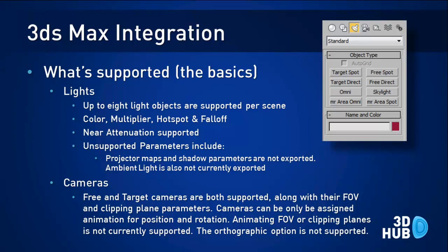And as far as cameras are concerned, free and target cameras, they're all supported. You can use the field of view, aspect ratios, clipping plane parameters. They all work. The only things that you can animate are the position and the rotation of the camera. We don't support things like field of view or clipping planes being animated, and we don't currently support orthographic cameras.